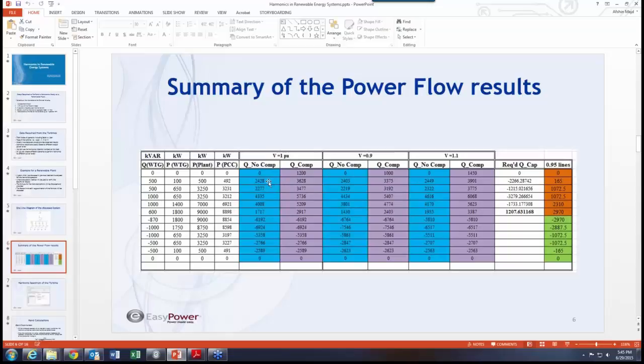When the voltage comes down, the plant generates less reactive power, even though every single turbine is generating the same reactive power. It's just the impact of voltage on reactive power. And we see that when the voltage goes up, the same plant has more capability and can generate more reactive power, even though, again, it's the same type of turbine and the same amount of Q, just by the change of voltage.